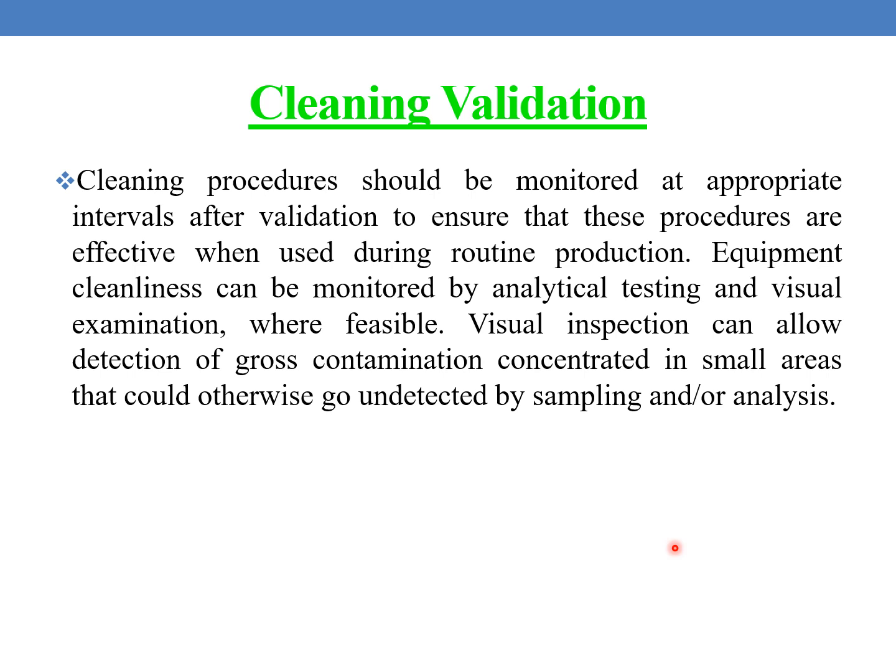Visual inspection can allow detection of gross contamination concentrated in small areas that could otherwise go undetected by sampling and analysis. So along with cleaning procedures, visual inspection must also be done for the detection of gross contamination.